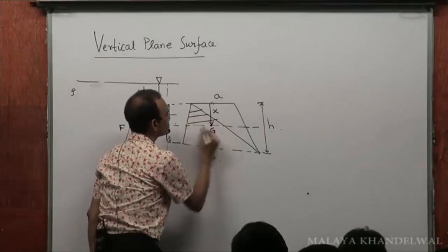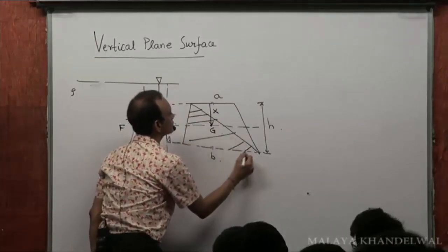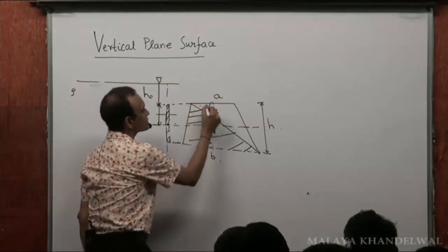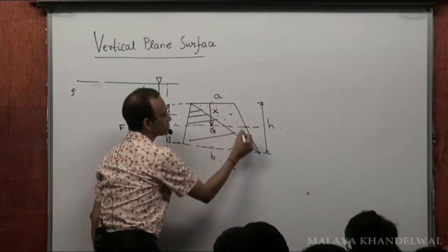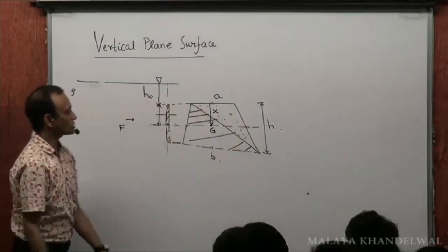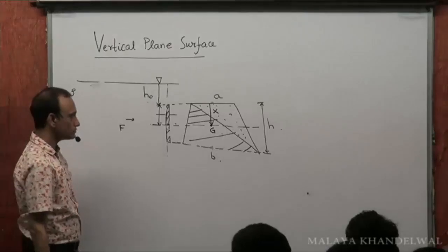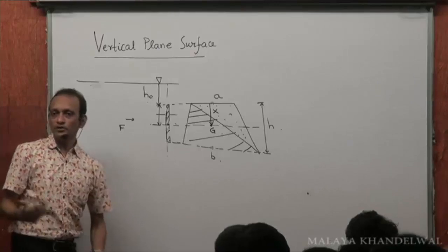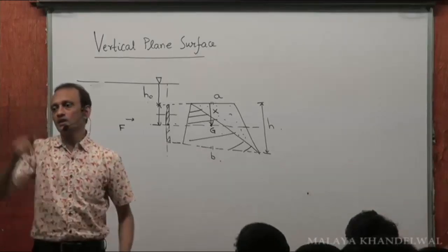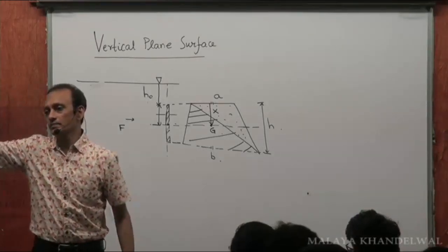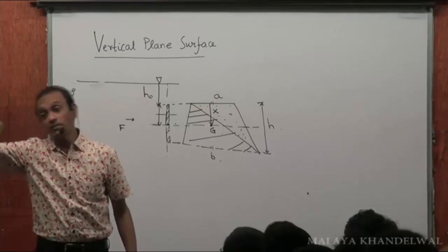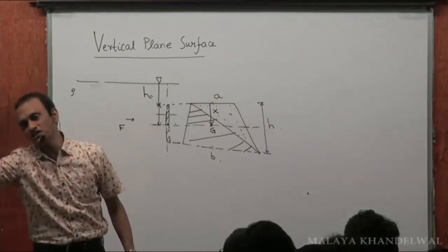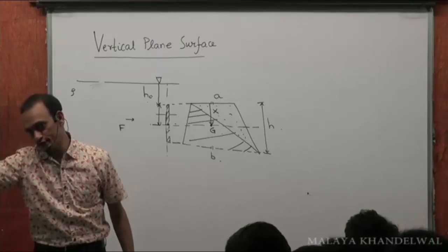This is one triangle, the shaded triangle, and this is the dotted triangle. Now, to compute the center of gravity, what do we do? Summation mixi by summation mi. The masses can be replaced by areas because masses are proportional to areas, right?